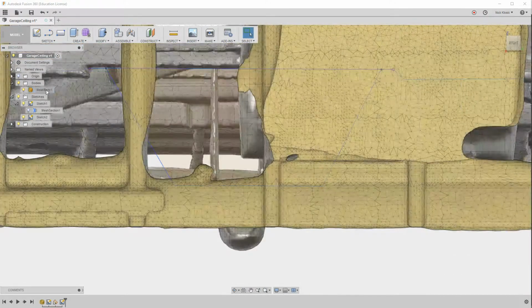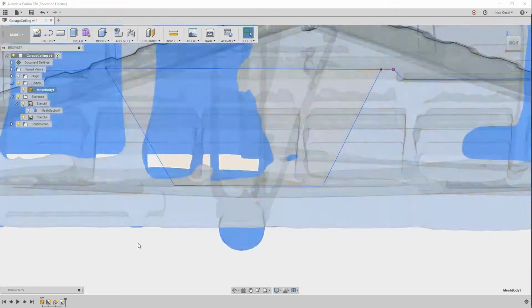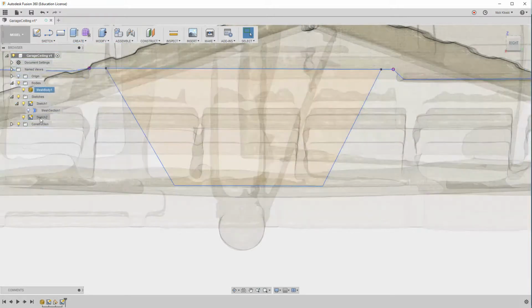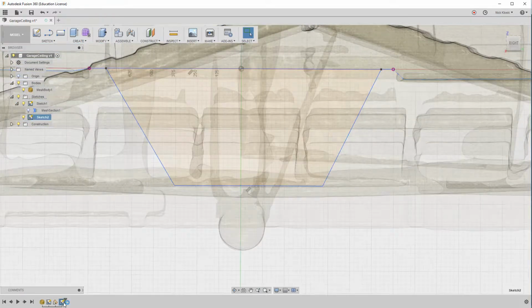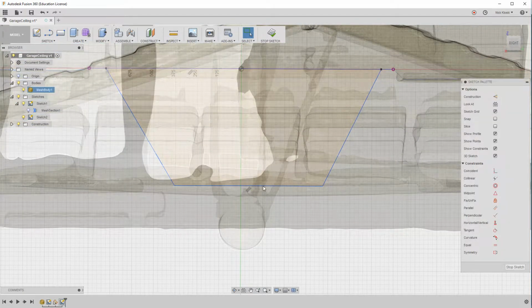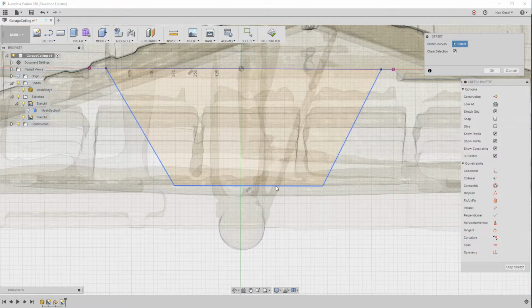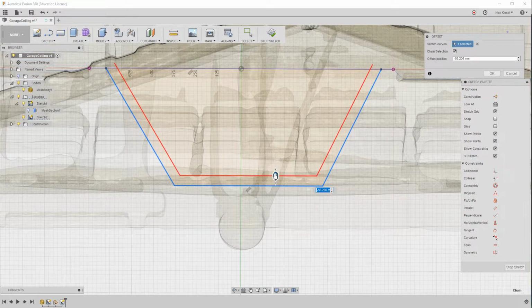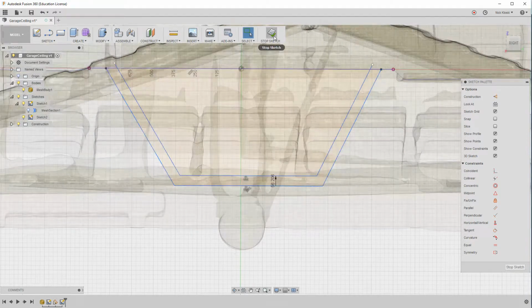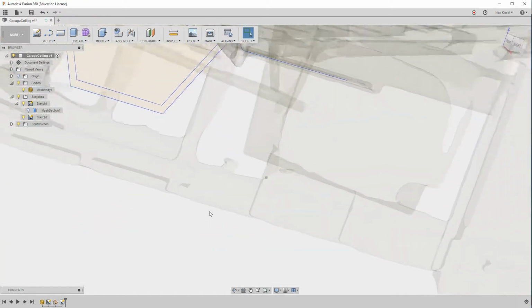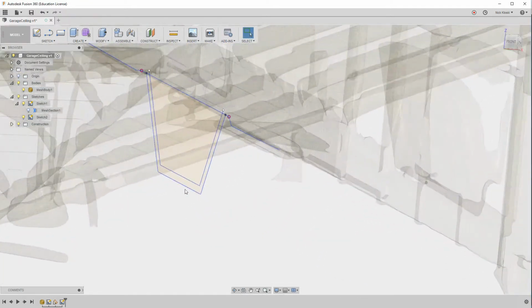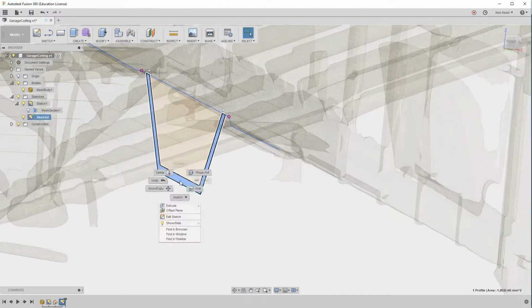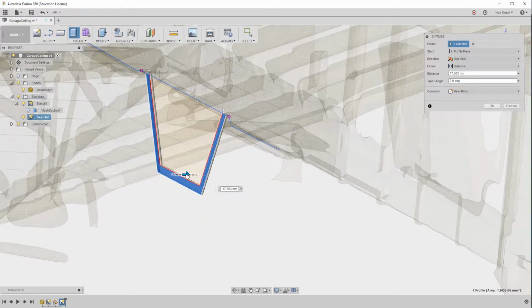Let me make this a little bit more opaque. Like this, opacity, I'll just turn it down to 10% so I can see through it and go back to my sketch right here. And so I can offset this, something like that. And if I wanted to build something that would go here, I could now take this out and extrude it a little bit.